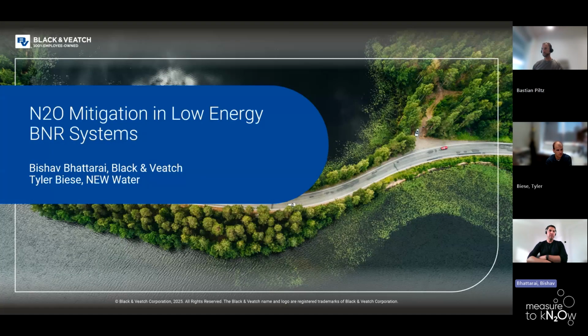In terms of the carbon dosing strategy, right now we're not looking at the NOx value when adding carbon. We're adding a fixed volume of carbon using the control timer, at the start of each anoxic phase. And the corresponding emission factors with MicroC is scary. It's more than 4 or 5.